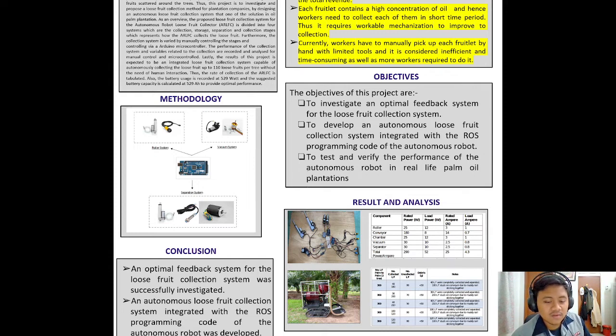So how it functions is it uses one linear motor actuator and two inductive proximity sensors. These inductive proximity sensors function the same way as IR sensors, only they detect metal surfaces. So in our case, we use these two inductive proximity sensors and one linear motor actuator to control the closing and opening of the chamber lid.